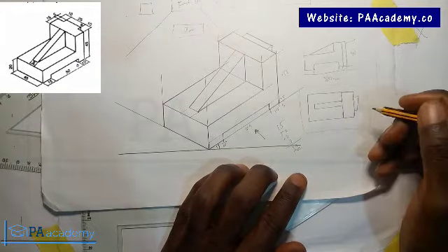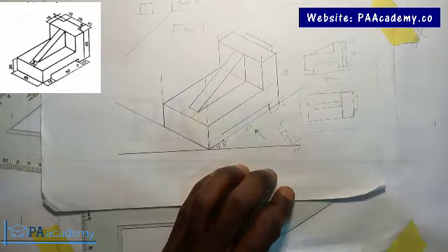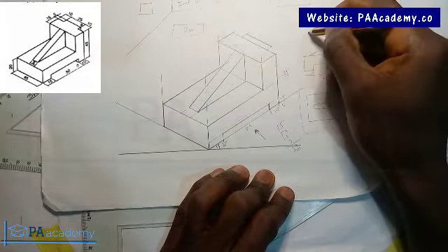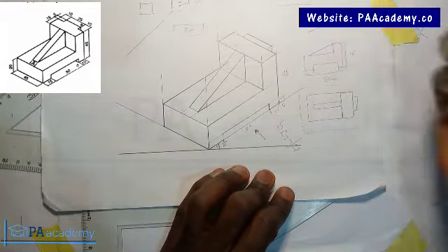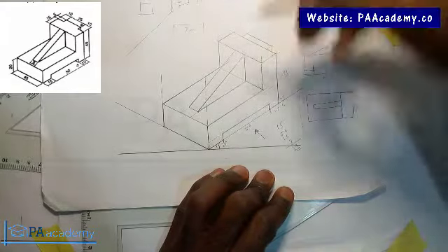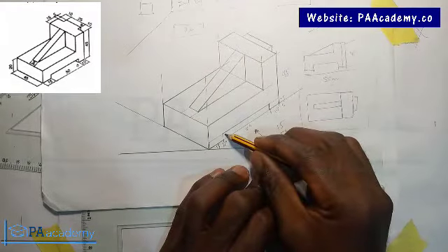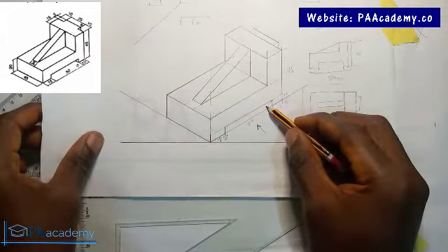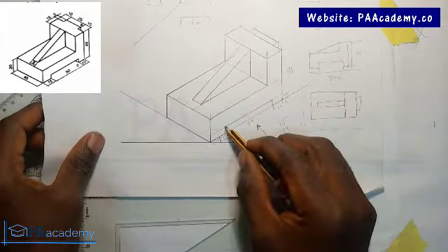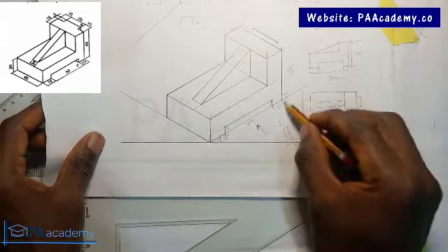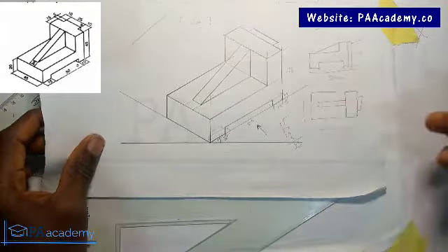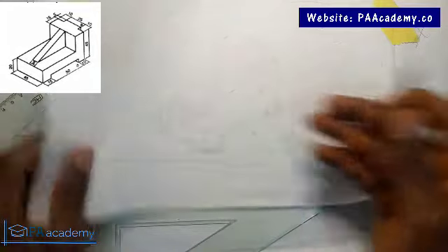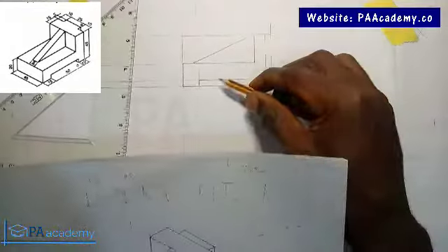But once you are dealing with first angle projection, there's what we call hidden details. And if you're familiar with technical drawing, we represent it with short dashes. What are hidden details? Now, if you are looking at it from the top, if you look at this place here, you see that there is an opening underneath it. Just like, let's just say this right here is a support, just like you have your table or your bench. This is like an open space that extends underneath it. Exactly. So this space here.